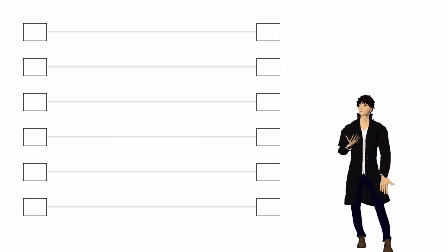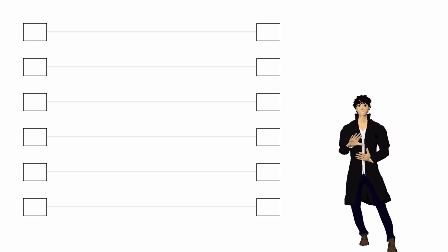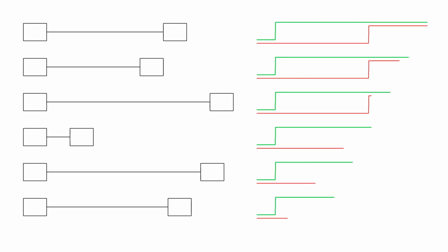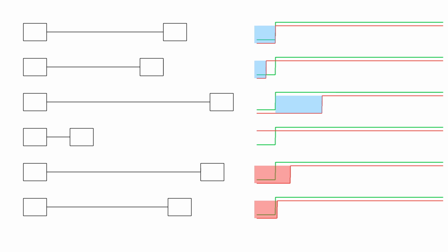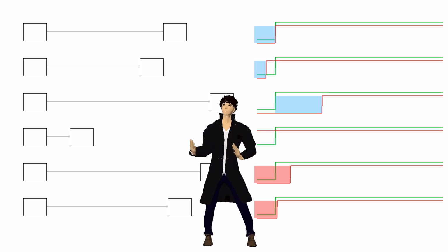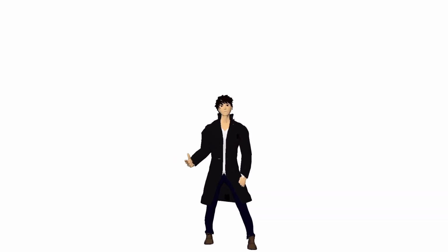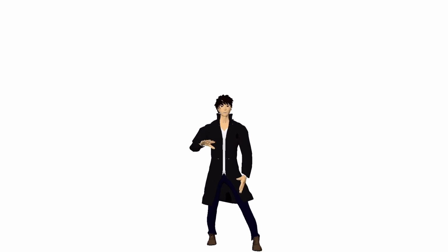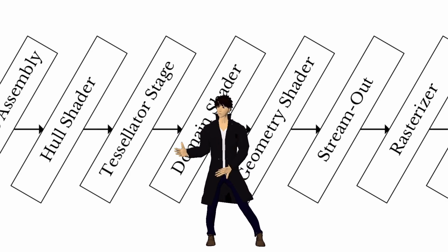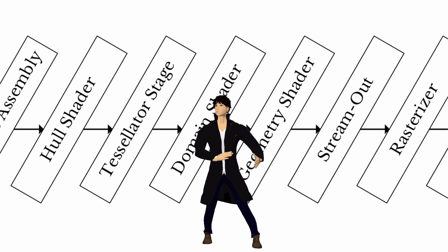Well, we think about each bit of a multi-bit bus as having an identical path through the design, because RTL-wise it does. In reality, there are slight differences in the travel times. So while a single bit is perfectly fine, another bit might have a problem. This window of acceptable relative clock phases is slightly different for each bit. But you want to guarantee that all the bits are correct at this output so that your data is correct going into the next compute stage of your pipeline.